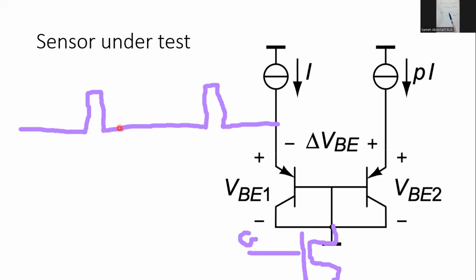Of course, ideally speaking, whenever your sensor is turned off, that means that this is ideally an open circuit, which means that basically there is no power dissipation, because in an open circuit, current is equal to 0. However, with a deep understanding of MOSFETs in CMOS technology, you can know that, practically speaking, in the off mode or in the sub-threshold mode, your current dissipated in a MOSFET is not ideally 0.